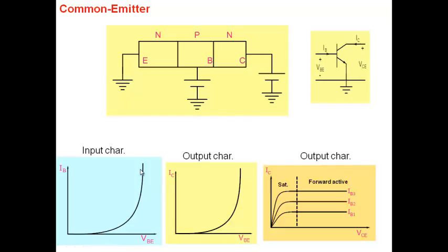So whenever you want a diode, you never try to achieve a certain current flowing through the diode by trying to apply a particular fixed voltage. You don't do that because that's highly unstable. Okay? So what you do is, by using an external resistor and other things like that, you control how much current is flowing through the diode. Use the external circuit to control the current. Otherwise, the diode is very sensitive to the voltage here. You don't apply a fixed voltage.